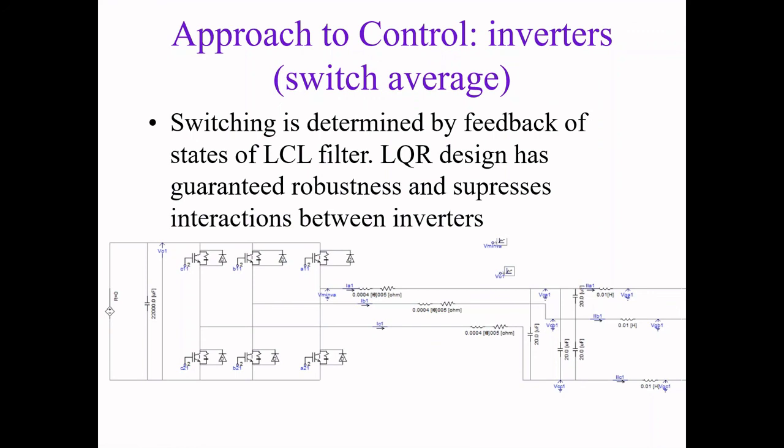Now, traditionally, a lot of the inverter designs are based on single loop current controllers. The difficulty that I've got is that a lot of the stabilization of these is very heuristic. There's no well-developed control design unless you make them a lot slower than they need to be. And so in this context, I've tended to adopt the linear quadratic regulator approach for controlling the inverter, controlling it as a current source, controlling it as a voltage source is much the same degree, but it's a fairly automated mechanism of coming up with controls with a guaranteed level of robustness, which is one of the big benefits of the linear quadratic regulators.